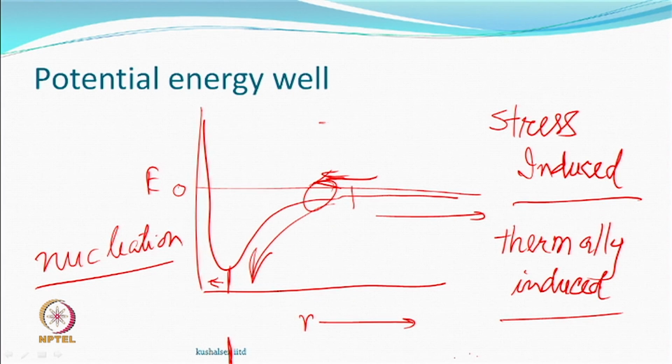So, by stress you initiate the process. Once this process is initiated, then you heat, then the molecules may say, well, it is not a bad idea, because it is possible to come close. And therefore, in polymeric systems, sometimes you see what we call chain folding. The crystallization happens, the chains start folding over each other because you gave them enough opportunity to do the folding also, and that becomes a crystallization.